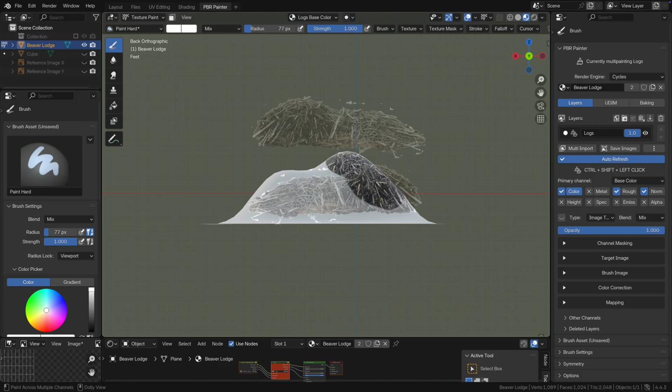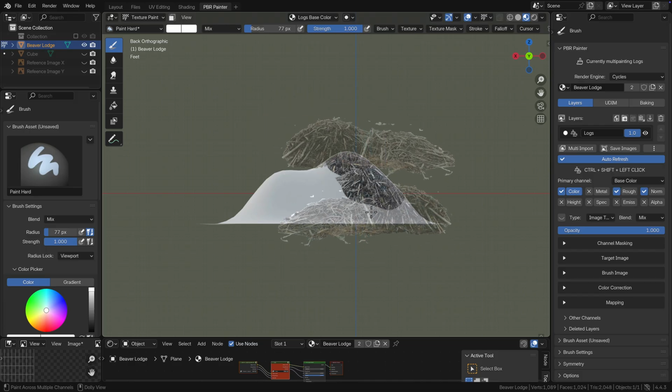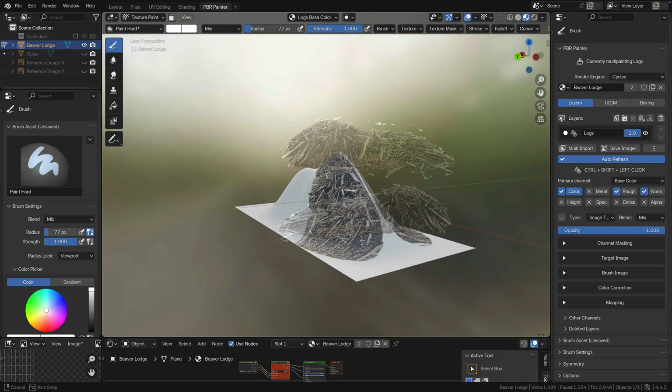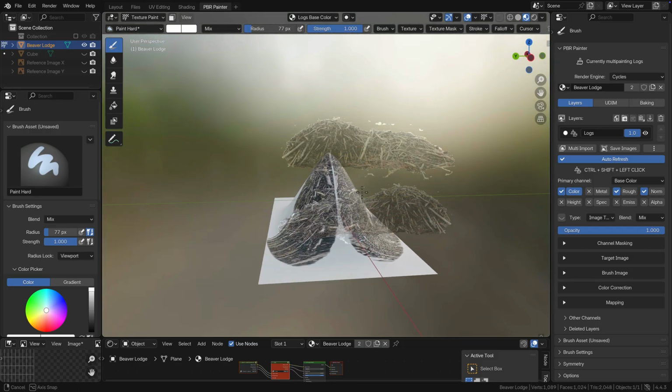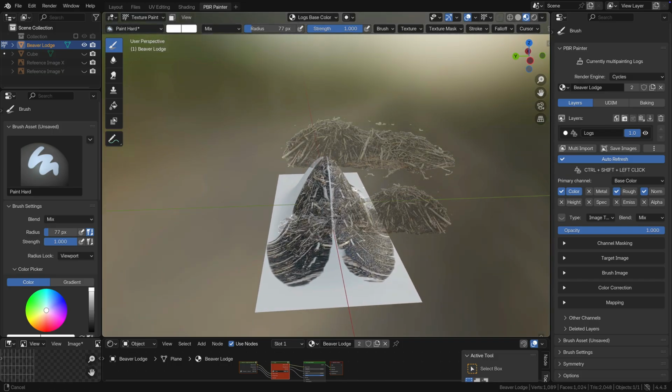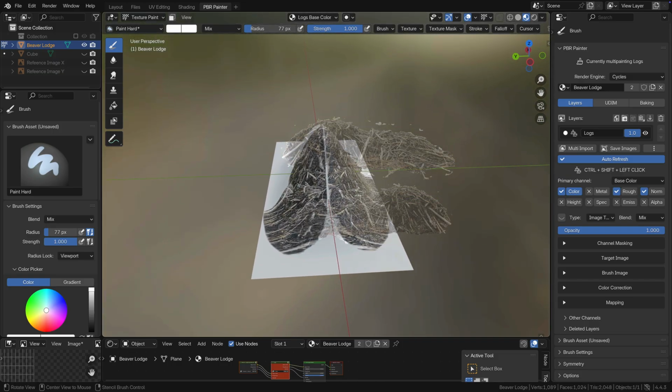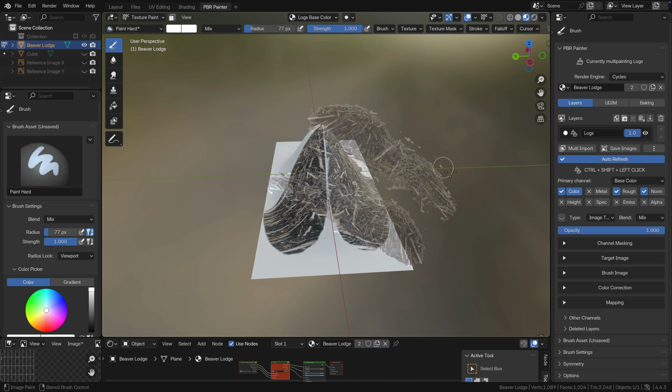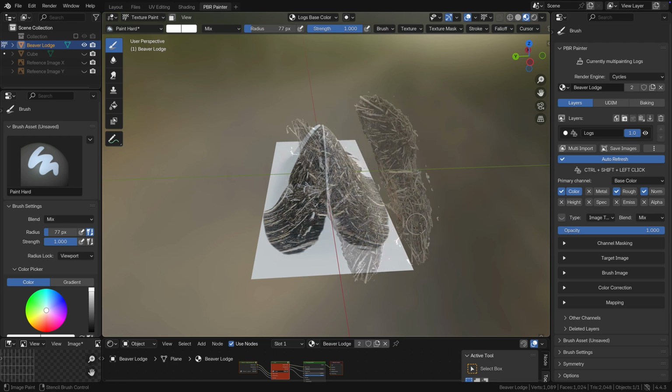I have programmed to rotate a mesh to the Option key and pan to the Option plus the Command keys. So for a mesh, leftmost button and dragging moves the mesh. Option and leftmost button dragging rotates the mesh, and Option plus Command and leftmost button dragging pans the mesh.